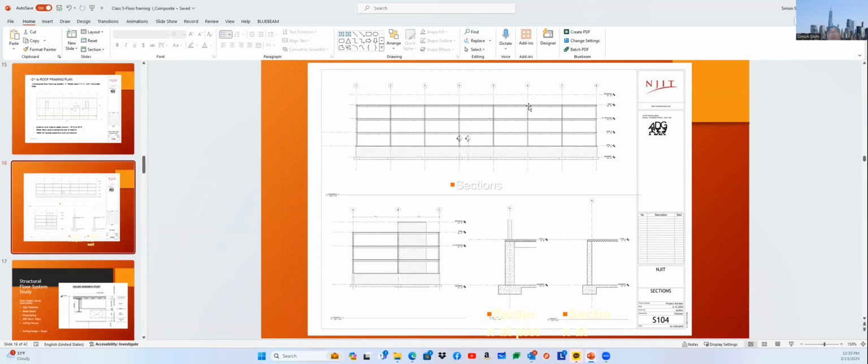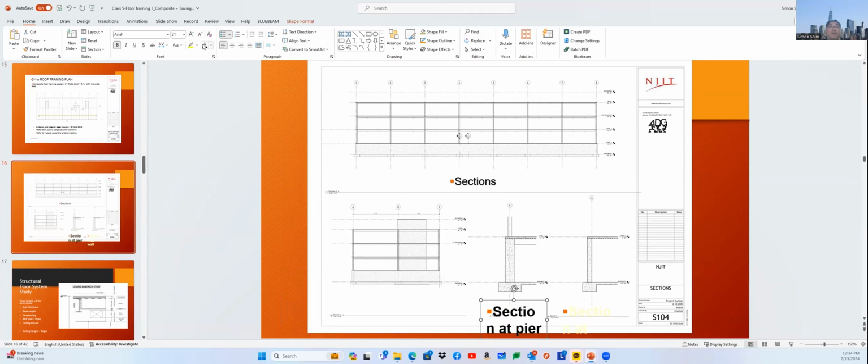And now the section. I made this as a Revit structure model for architectural students' presentation, to guide them. You can see the foundations and their interactions: the steel column is sitting on the concrete pier at the grid line. Obviously, you'll see that the metal deck slab is parallel to your wall. So there will be some slightly different sections between these two, at the column grid or off grid.